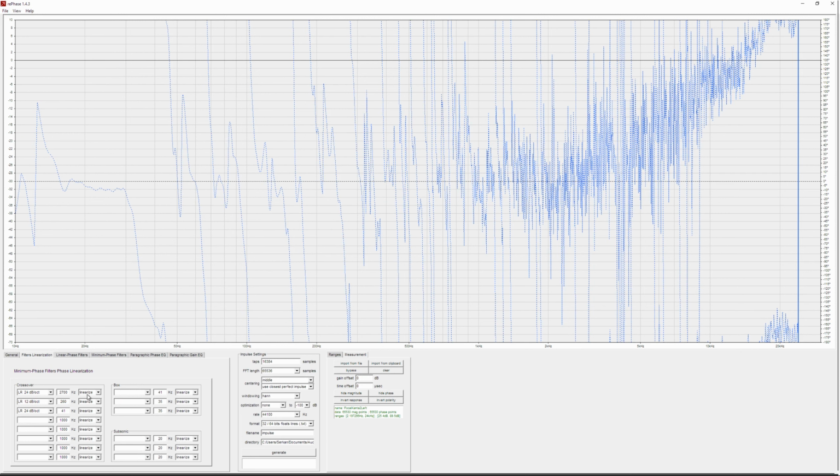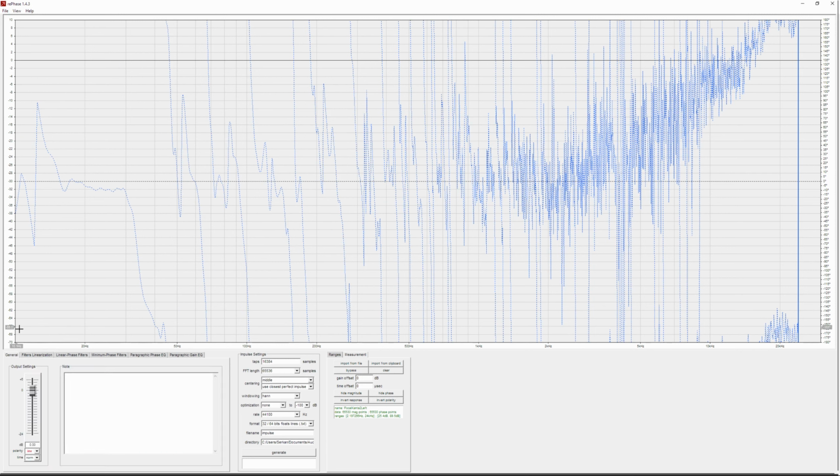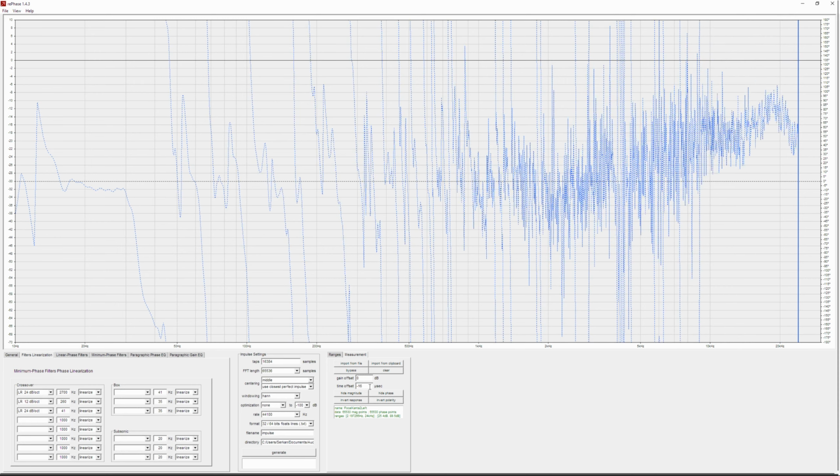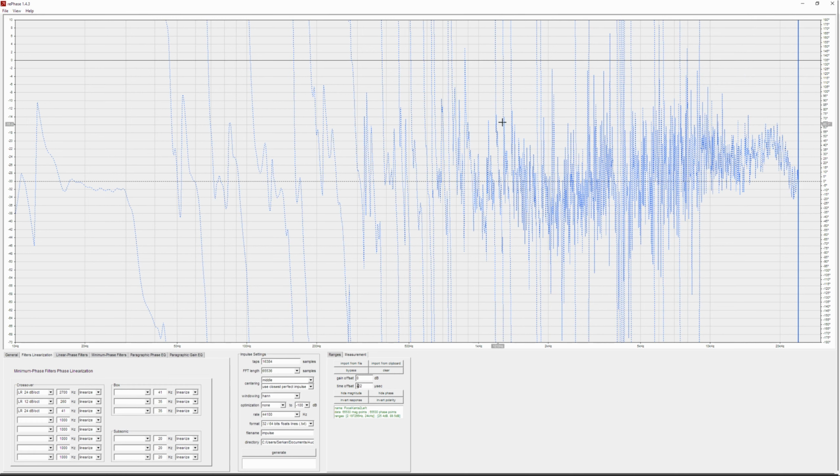The normal way is quite complicated, as you see, with polarity inverted on all three of them by coincidence. And if you pseudo align the timing of the speaker here, bringing the highest measured frequency, which arrives first to the microphone, to axis 0, it's pretty flat now throughout the frequency band. So this seems to be my phase correction.